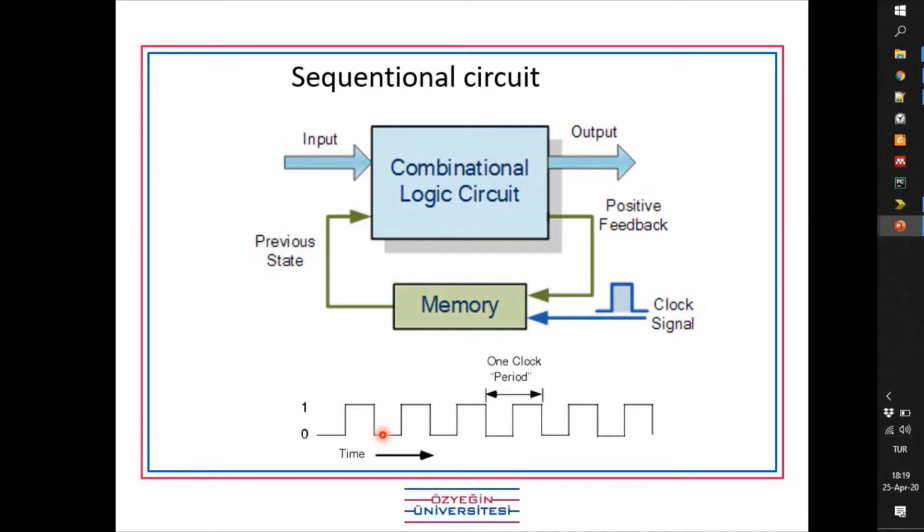So in our FPGA designing in Verilog, we use the positive edge. Positive edge means when the clock is rising from 0 to 1. That means when the voltage is rising from 0 to 5 volts. When it's changing from 0 to 1, that is when we save something. That is when our circuit is triggered, activated.